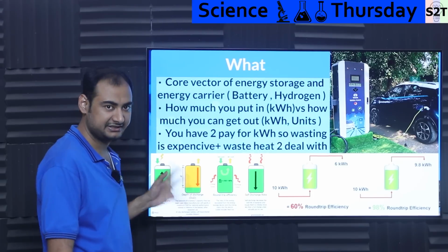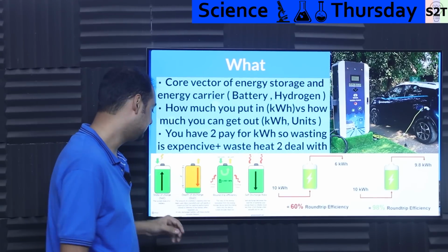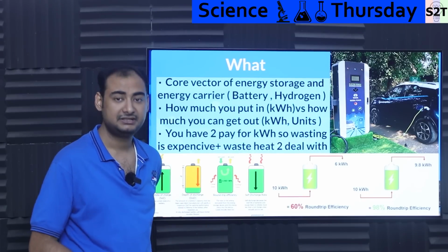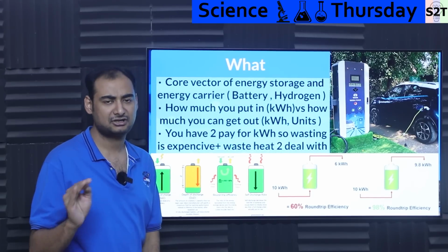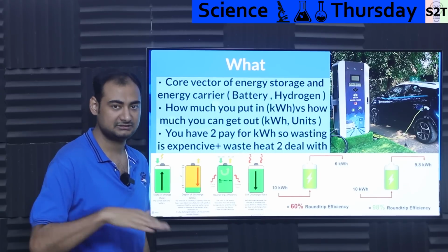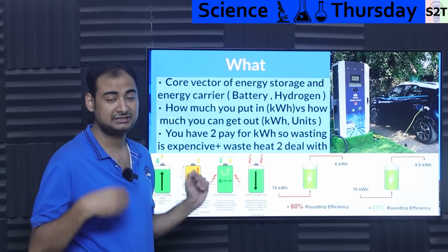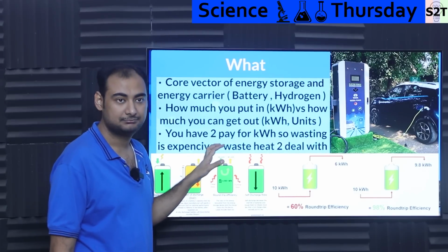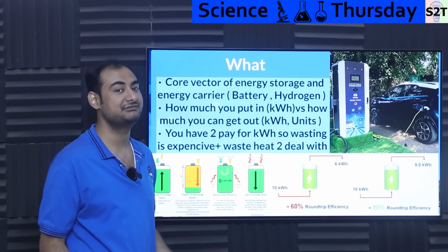And again, this is the battery's normal understanding. So you have state of charge, basically how much charge it has, and then you have depth of discharge. Most BMS will not allow you to drain the battery to 0%, and most batteries will be bricked if you allow them to drain to 0%. So generally there is a cutoff at, let's say, 5% or 10% or 15%. There would be a cutoff point, and the BMS will not allow you to go below that. And then you have round trip efficiency that directly affects the internal resistance of the cell, basically how much energy you are wasting when you are putting in energy, and how much energy you are wasting while you are pulling out. Yes, both times it wastes energy.